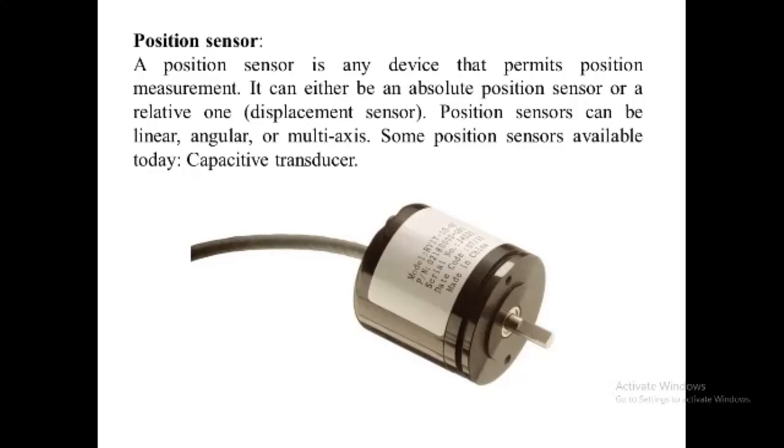But there is one main disadvantage of using the potentiometer as a positional sensor. The range of the movement of its wiper or slider, and hence the output signal, is often limited to the physical size of the potentiometer being used. For example, a single turn rotational potentiometer generally only has a fixed electrical rotation between about 240 to 330 degrees. However, multi-turn pots of up to 3600 degrees of electrical rotation are also available.